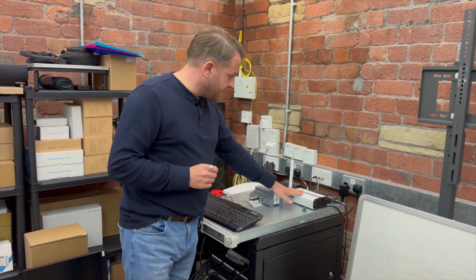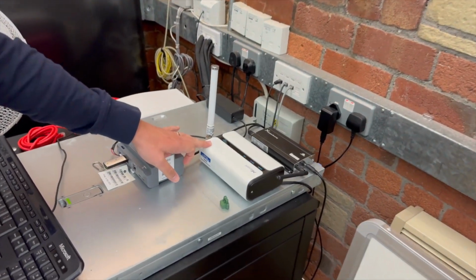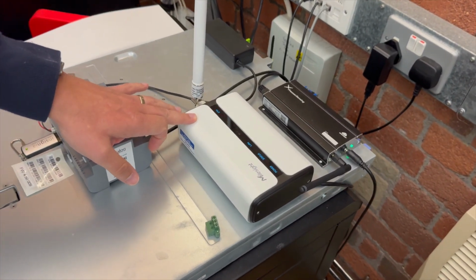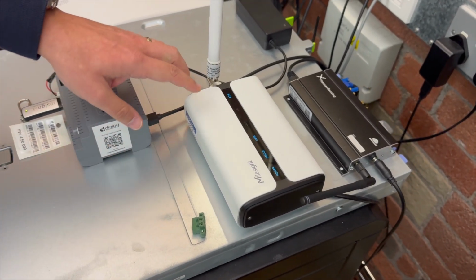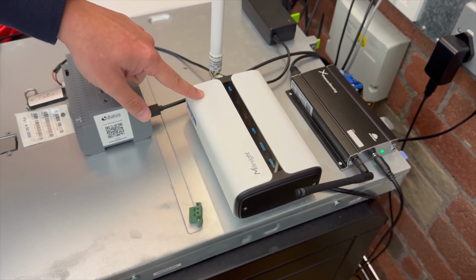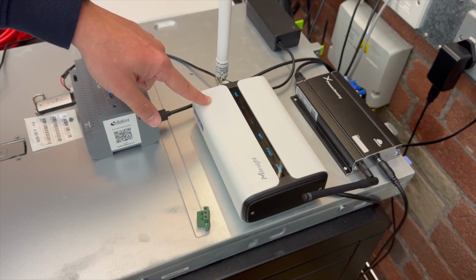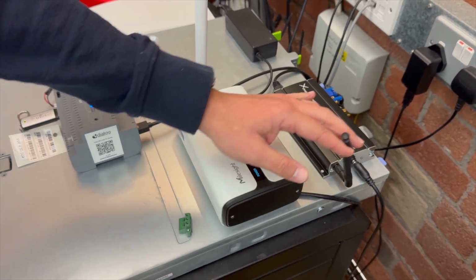These two devices here are the gateways I told you about. So you have the MileSight LoRaWAN gateway. In built-up areas, there's a 2-kilometer radius for connecting to a sensor, and in non-built-up areas, you can go up to 15 kilometers. And then this is the Presac EnOcean one.